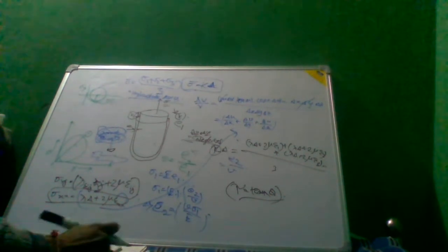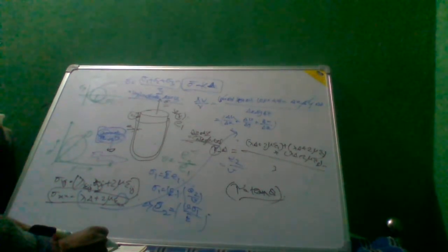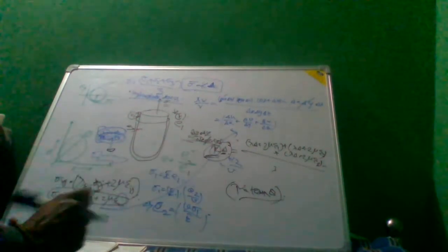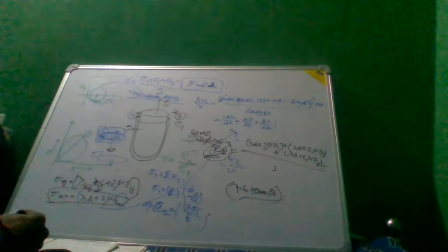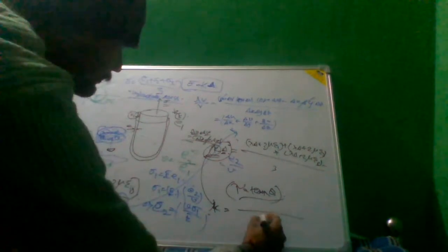That is the total change, where the bulk modulus is the incompressibility experienced by the body under hydrostatic pressure P, the negative of the pressure being in equilibrium. So the applied stress acting on the surface for each of the directions will be added and divided by 3, and K will be obtained from this equation.